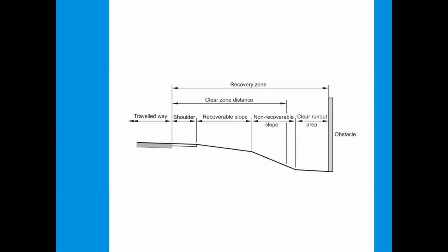Steel fragile posts fold on impact as a result of shear failure planes. Aluminium assemblies collapse due to the shear pin action. Fragile wooden signposts have holes drilled at the base, creating a plane of weakness that permits the post to collapse on impact.